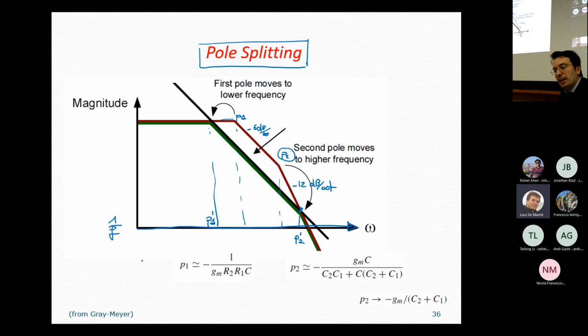Concerning the common source, this is transistor 6. So we have GM6 as the transconductance, and the output resistance is given by 1 over GO6 plus GO7. Okay, so the parallel between the output conductance of transistor number 6 and the output conductance of transistor number 7. Okay, so this is basically the DC gain of the two-stage amplifier.